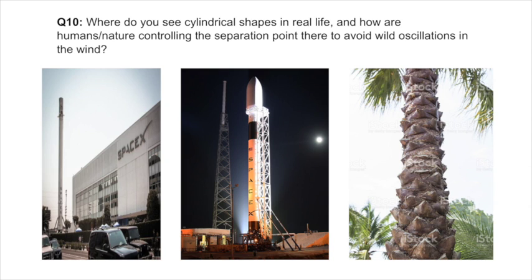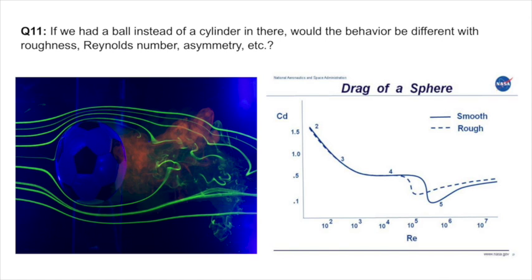The aberrations on a palm tree will increase the drag because drag depends on flow in the boundary layer, and the boundary layer occurs exactly where the aberrations are, so the surface is extremely important to an object when examining the airflow. Yes, roughness of the surface just depends on what material is used, but what affects behavior and how much drag exists, the shape and size of the surface and object is critical. Reynolds number depends on characteristic length, so if the diameter of the sphere is different than the length of the cylinder, I think Reynolds number would change.